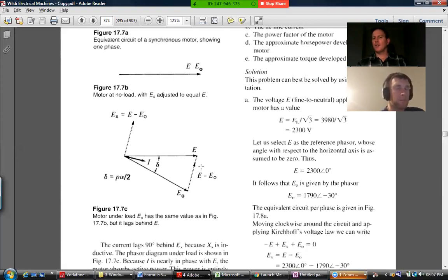It's a bit complicated in the sense that the stator is seeing two voltages. It's seeing the grid voltage and it's seeing the induced voltage at the same time. They're superimposed, so to speak. And it's that difference which is actually making current flow in that stator. So once we've got those two vectors, again, this one is not necessarily the same size. If this was a certain voltage and this one was the same size, we would typically call that neither over nor under excited. We'd say it would be the rated amount.